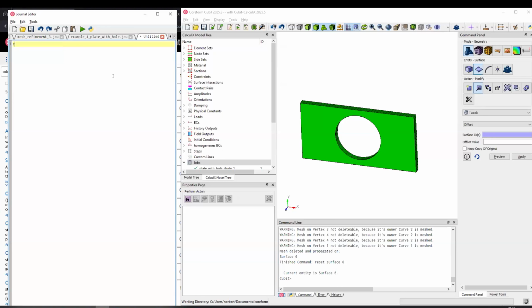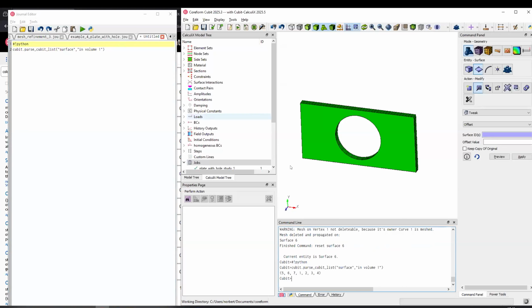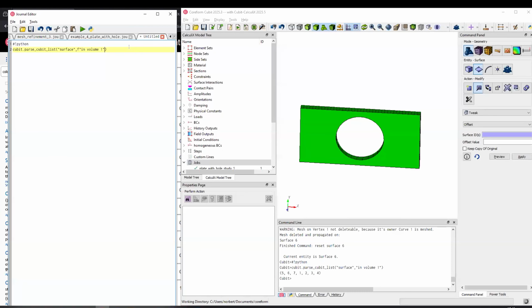So how does he pass in that integer into that parse qubit list? Yeah, we can just do it. Yep, and we kind of glossed over a little bit, or didn't gloss over, but we mentioned or introduced F strings, where the F is short for formatted. So it's a formatted string, and that is a Python functionality. So what Norbert's doing here is, if he takes a string and he puts it, I will just show what's hard-coded here, and then we will insert the F string. So now we got all surfaces from volume 1, of course, but we just need to put an F before the string that we want to be formatted. We need to use this bracket, and yeah, I will just hit ID2, because then nothing should happen. The list should return nothing.